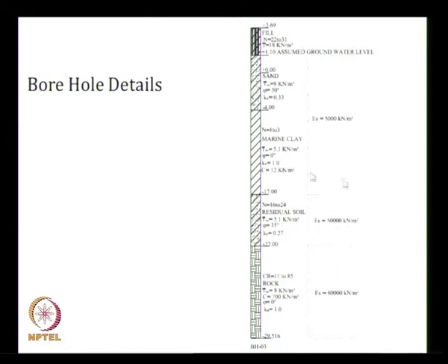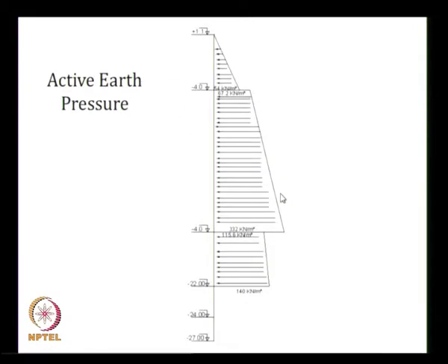So these borehole details are very important. If you are designing a structure and want to economize it, in the foundation, if you do it properly, we can economize 10 to 15%, in structures only 2 to 3%. So if you are a structural engineer you cannot give much optimization, but if you do thorough analysis and foundation design, you can reduce the cost.